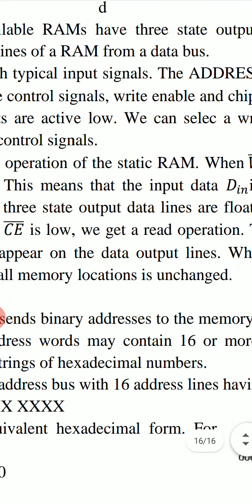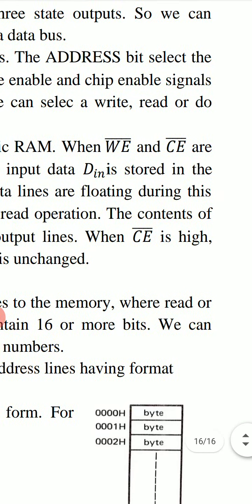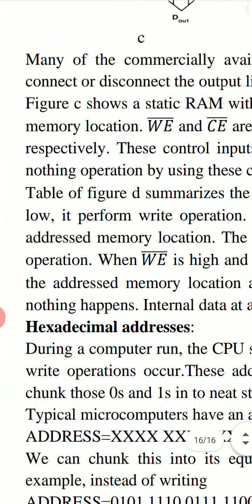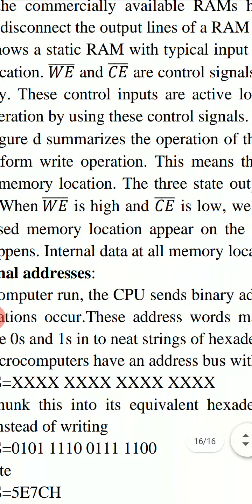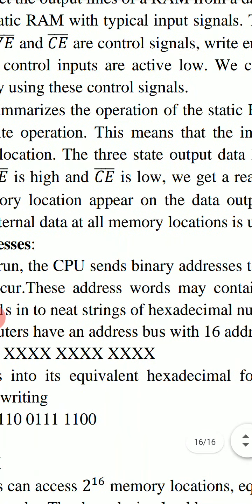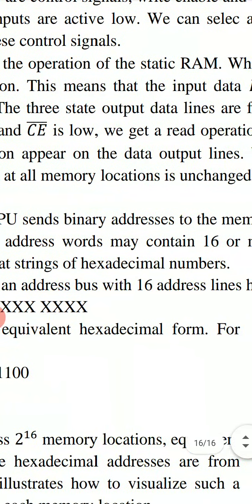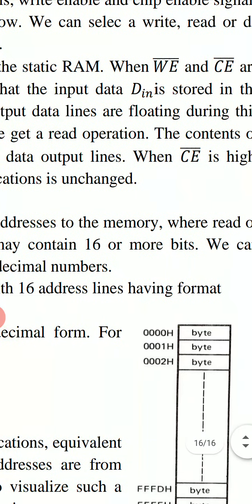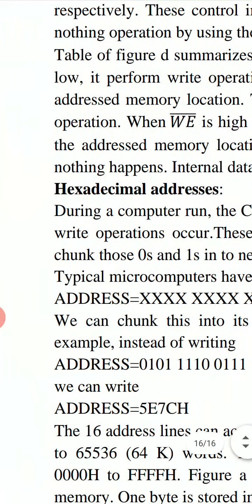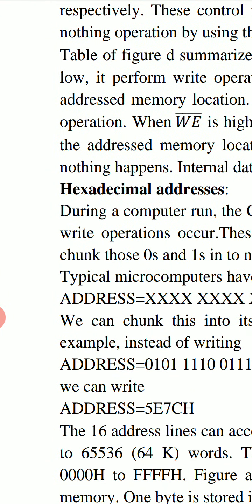This means that the input data D in is stored in the addressed memory location. The 3-state output data lines are floating during this operation.